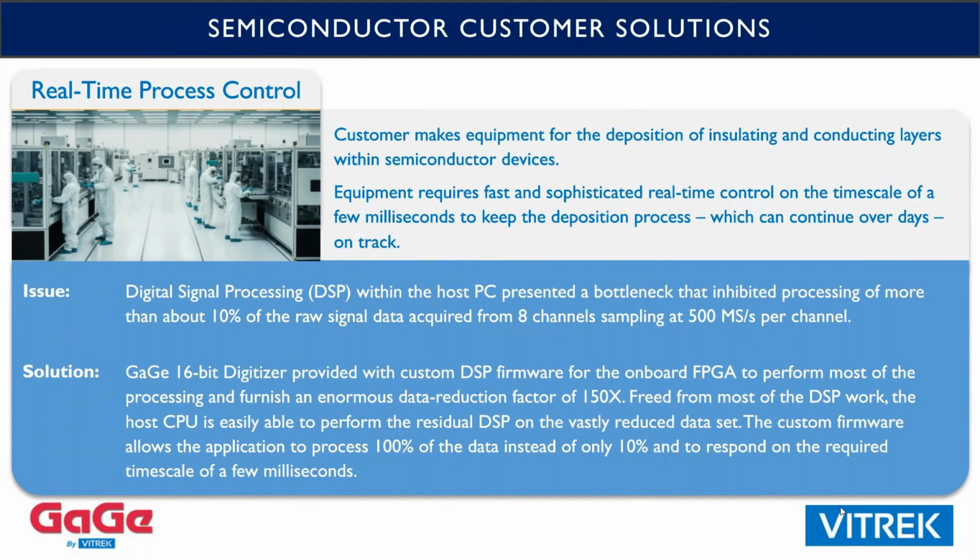So this presented problems for closing their feedback loop. So what we did for them: our cards are controlled by what we call an FPGA, a field programmable gate array. Normally, instrument cards like ours would be controlled by a much simpler general purpose multiprocessor. The problem is we need to move data around our cards so quickly from the ADCs to the memory and to the PCI bus at rates of several gigabytes per second, and you just can't do that with a microprocessor.